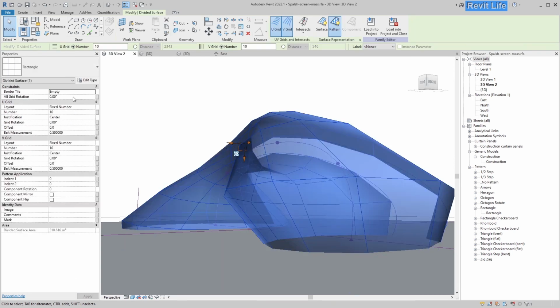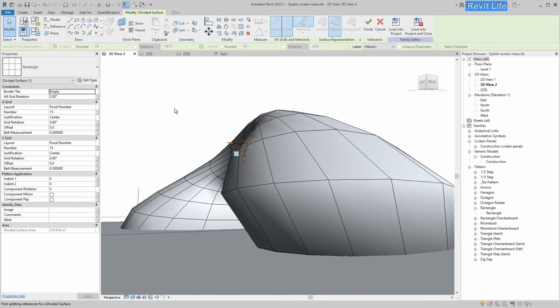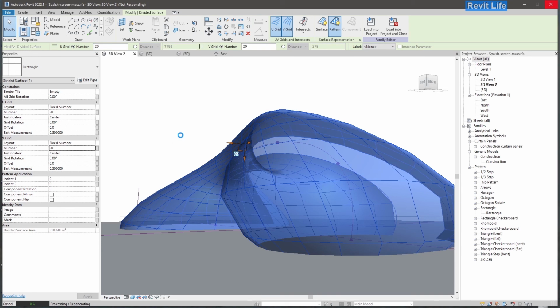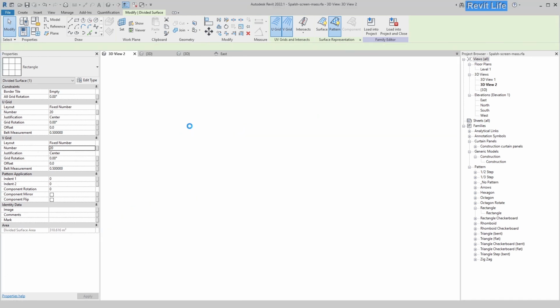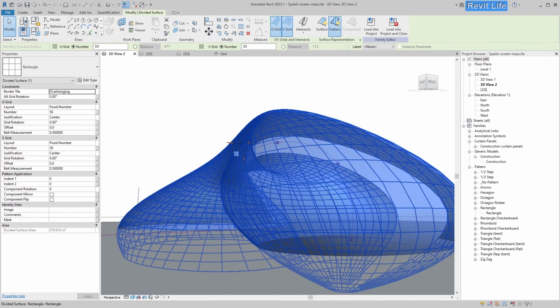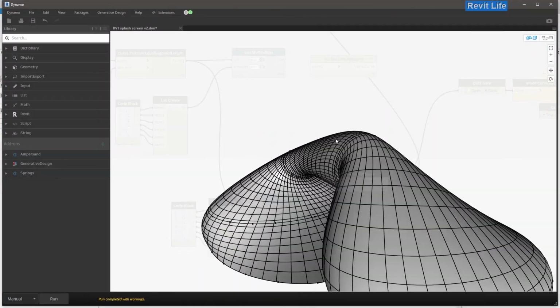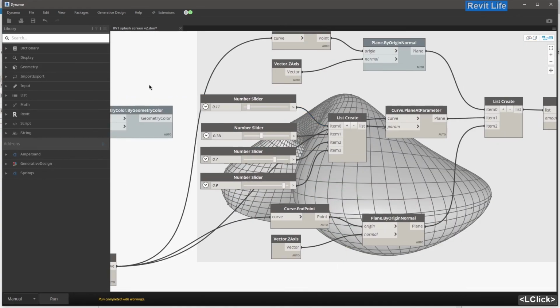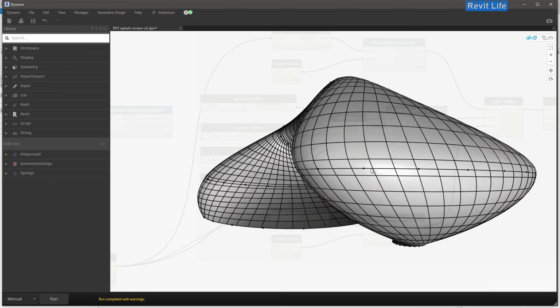It just threw an error that it cannot make this mass or this form, and it just wouldn't make the perpendicular tubes or pipes. And for a while I thought that the problem was in the surface or in the grid of the surface, because in some places the grid cells are too small or too narrow for the families to populate the exact pattern that I want.